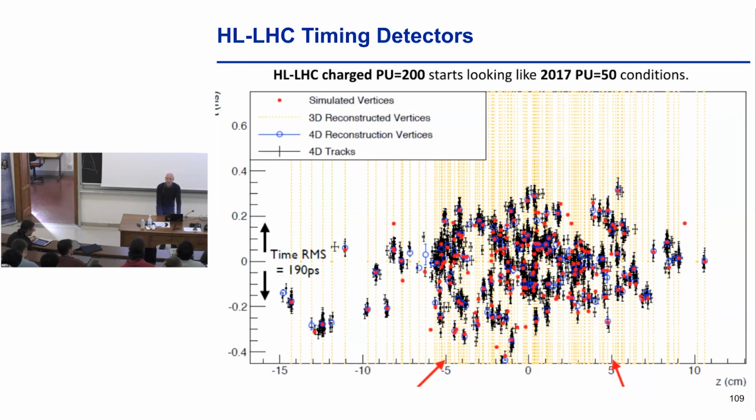Yeah, it is corrected. So the time walk, it is corrected. But now remember that we don't know that charge with infinite precision. We discretize it and we know it with only some accuracy. And then I have no idea, within that range, what is the exact value. So my correction can only be on average. So we correct the first order, and then we have the second order effects that enter the resolution. But absolutely, those corrections need to be made, otherwise that would actually be dominant. But those corrections are made offline in terms of calibration.